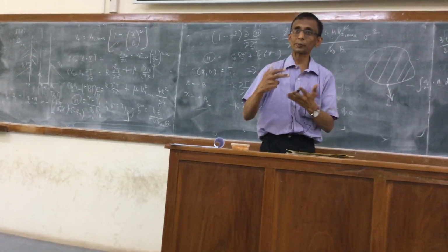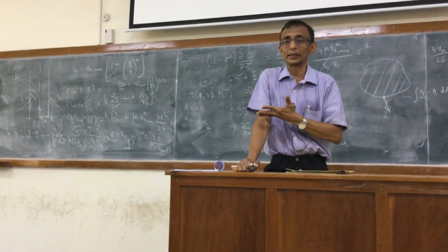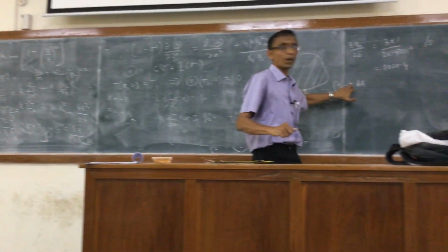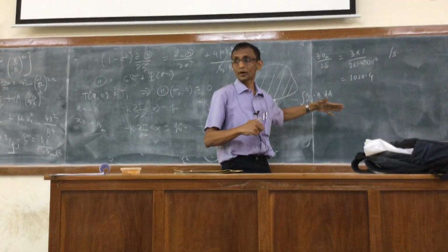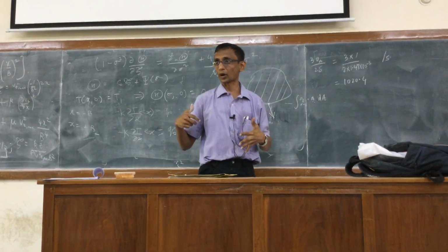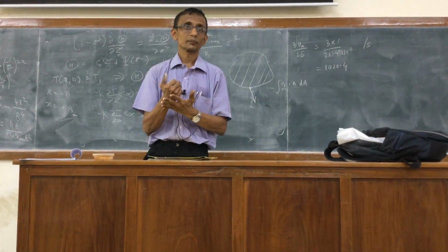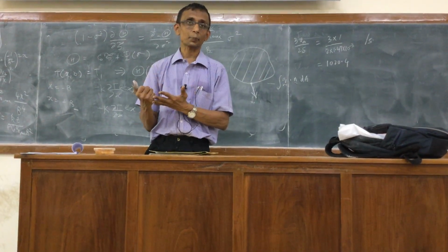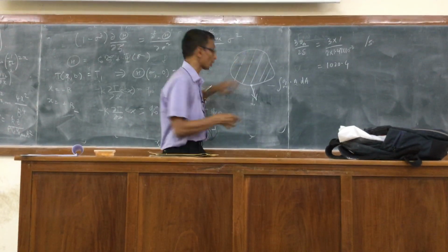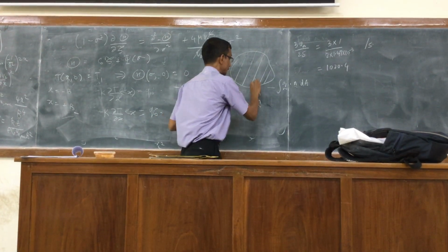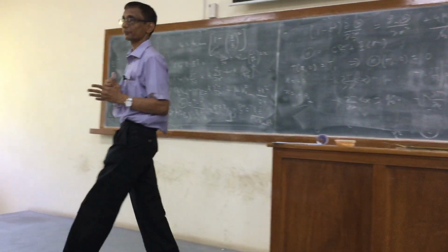The q always, by convention, because Fourier always uses minus k dT by dx, and q dot n is what is going out, because n is the outward normal. Since for us the heat coming in is to be treated as positive, this represents the heat coming into the body. This is only the outward normal, while the heat direction is coming in.